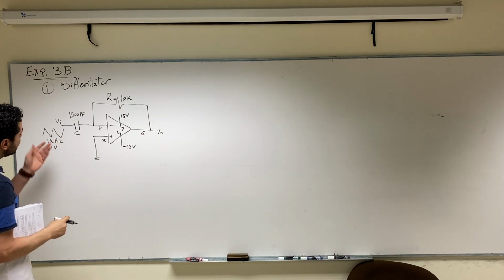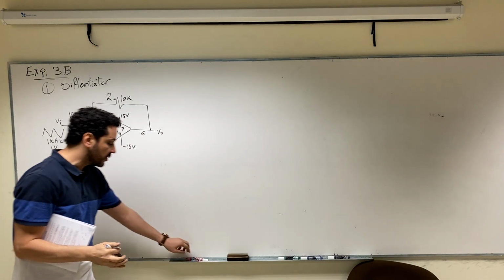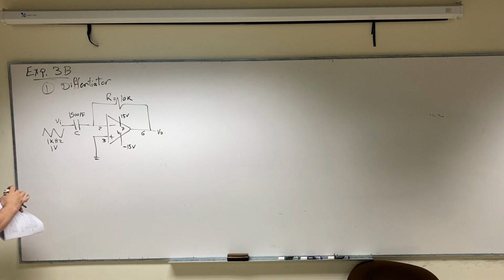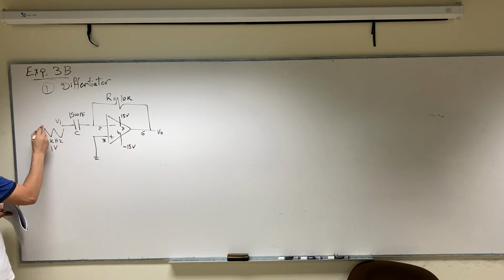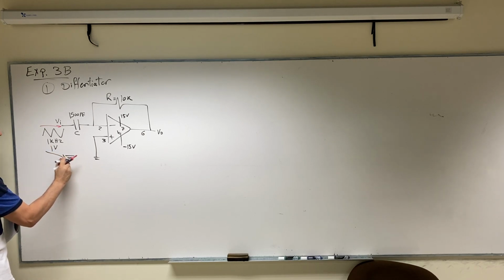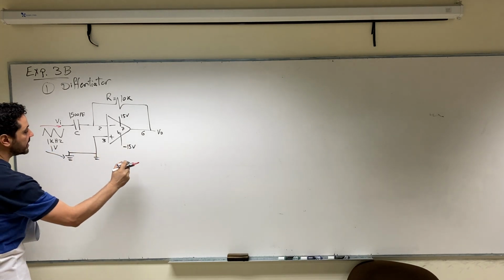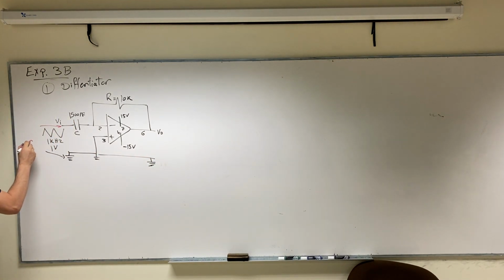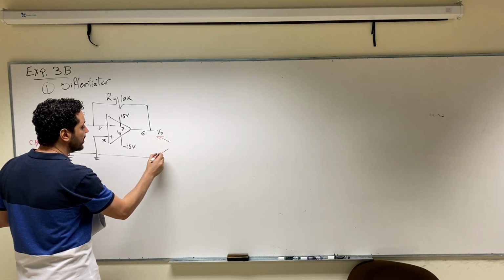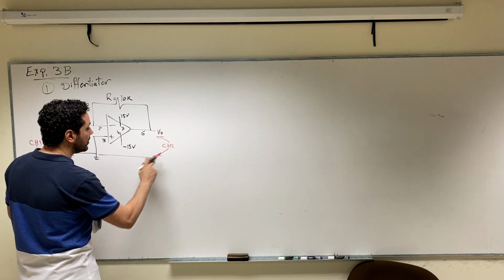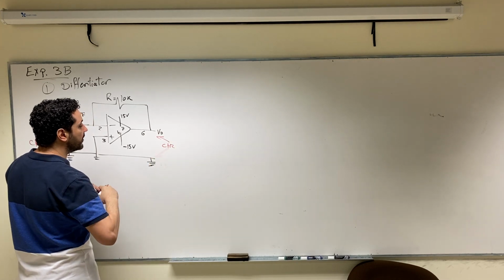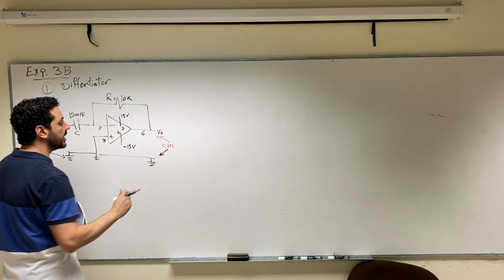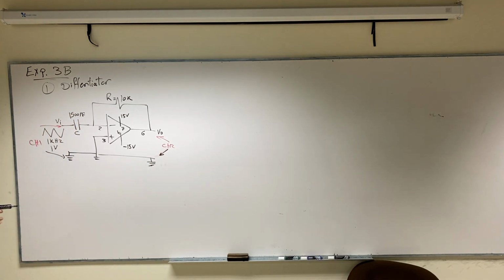How are we going to connect this? We are going to connect this from the function generator. So basically, you are going to take the wire coming from the function generator, connect the red terminal here and the black terminal to the ground, which is the same as the ground of the whole circuit. Okay, so the ground of the whole circuit. And by default, also channel number 1 of the oscilloscope will be connected here. Channel number 2 of the oscilloscope you connected here. So channel number 2, you should connect the red terminal of it to the output and the black terminal to the ground, okay, in order to watch the output signal.